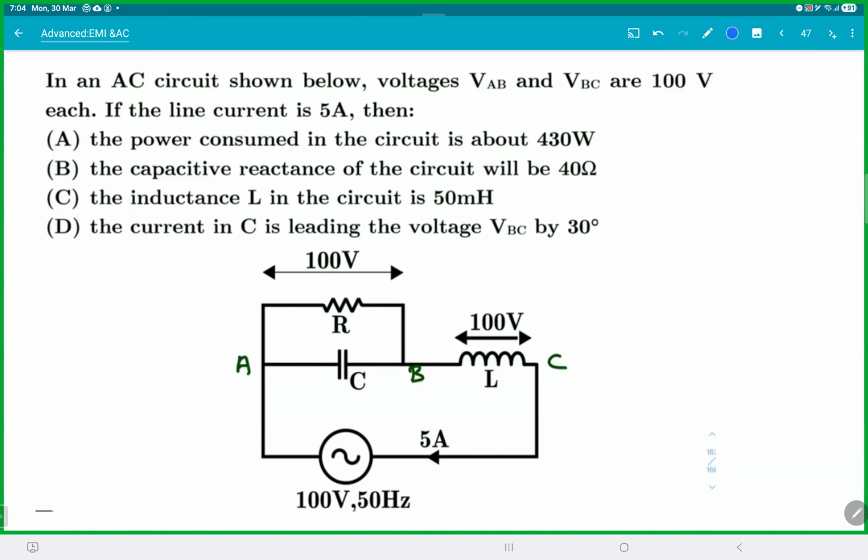So the voltage source, I will write this thing, V source. This thing is technically right, 100 root 2 angle 0. I will just write it as 100 angle 0. Okay, and I'm going to write all RMS values because I think they're also asking all RMS only. I'll keep it in RMS, but technically it should be 100 root 2 comma 0. It won't matter in the answer because the root 2 will cancel, but ideally you should always write 100 root 2 angle 0. Okay. So let's call this guy Z1. Let's call this guy Z2.